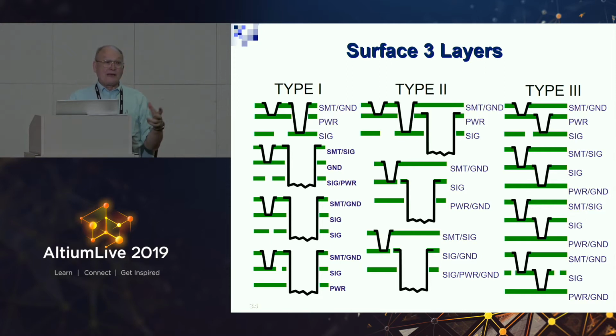And an anti-pad is the opening we have to make in the reference planes to make sure we don't short that drilled through hole. So they have no concept of the geometries involved here. But I can show them, and they walk away kind of with the tail between their legs, because I proved it. Look, you gain 32% more return path. This is by having that ground plane on the surface. And they're still scratching their heads, you know. Nobody's ever told me that before.